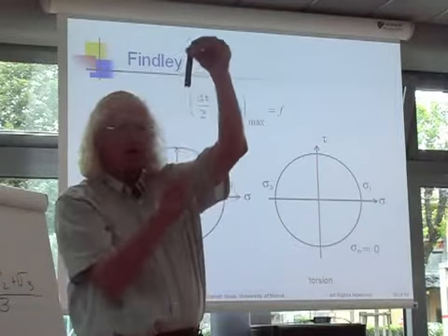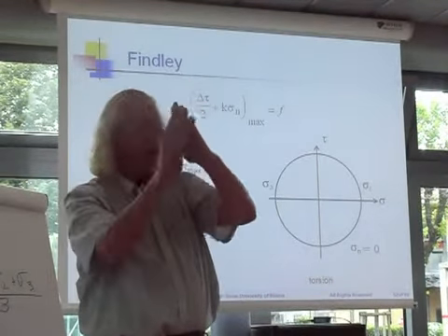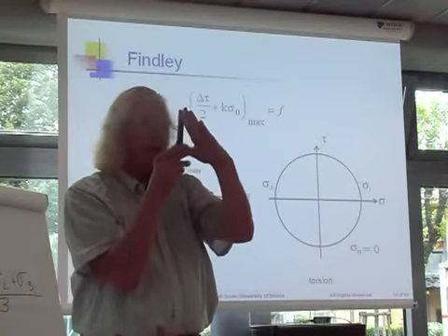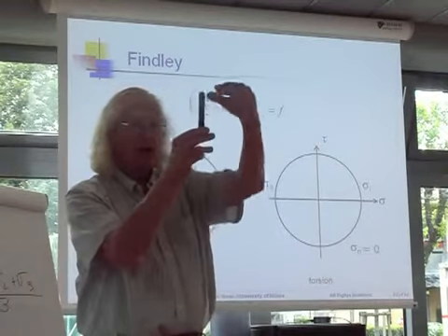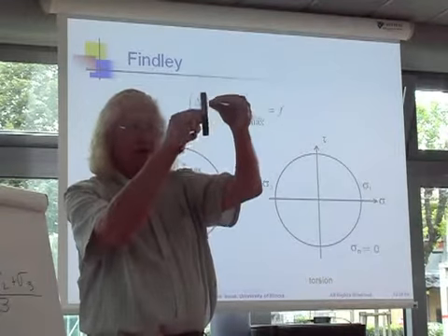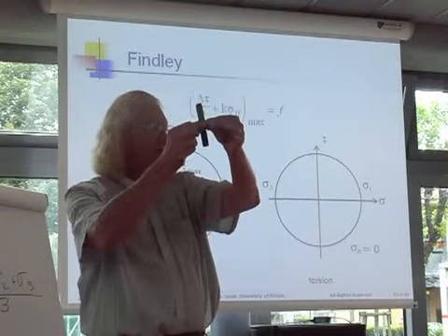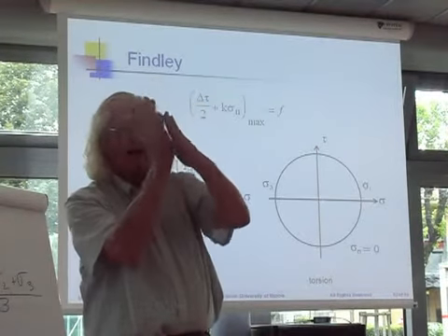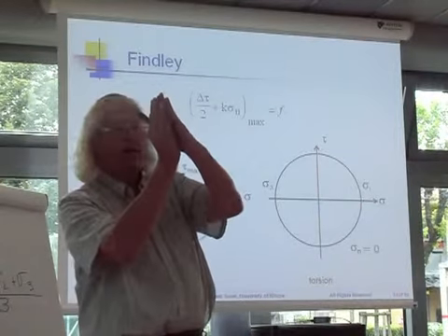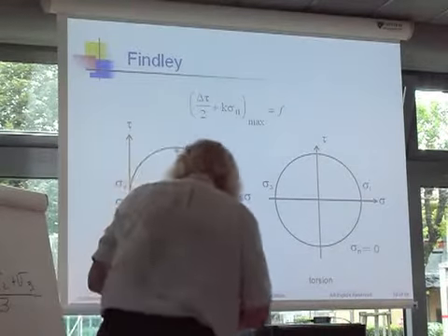So when I load this in a tension cycle, then I, of course, have a shear cycle that acts on this 45-degree plane. But in addition to a shear cycle, when I load this in tension, I also have a tension cycle on the same plane. So when I have a shear crack in tension, I'm not only shearing this crack, but I am opening it at the same time. And we see that for Mohr circle.